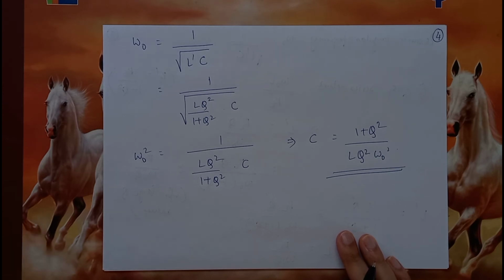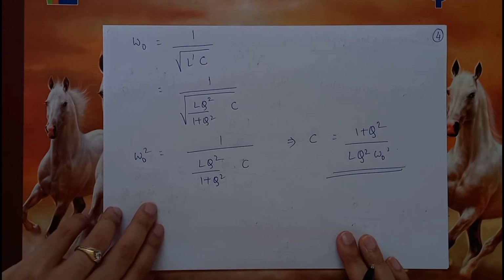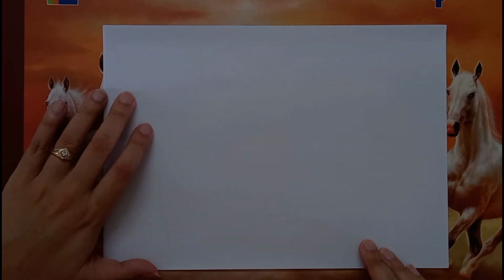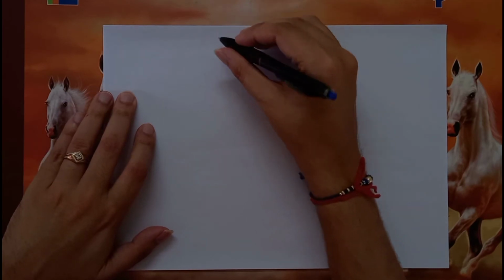So we saw one example using which we can find out the required values for an L-shaped matching network using L and C, to match some real load to a source having real impedance. So now, as I had mentioned in one of the previous lectures, in general, depending on the values of the impedance, 4 kinds of L-match networks are possible.